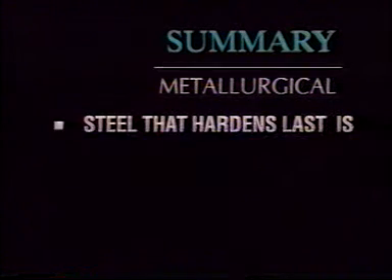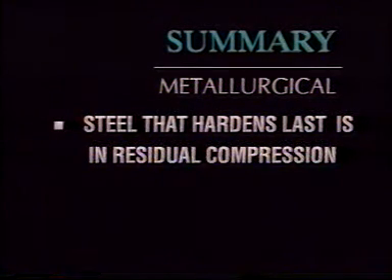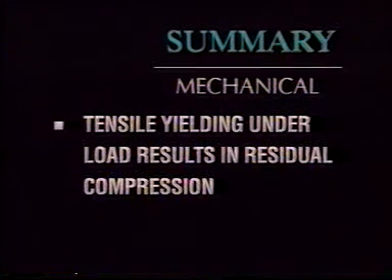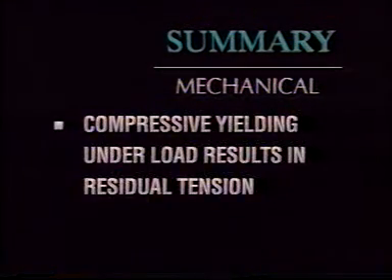Metallurgical residual stresses are induced because the steel that hardens last is in residual compression. Mechanical residual stresses are induced because tensile yielding under an applied load results in compressive residual stresses when the load is released. The opposite is also true of mechanical residual stresses. Compressive yielding under an applied load results in tensile residual stresses when the load is released.